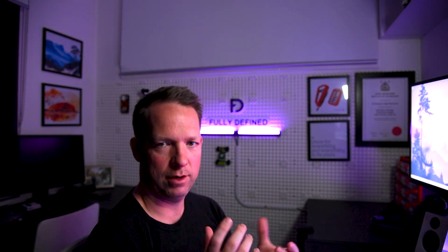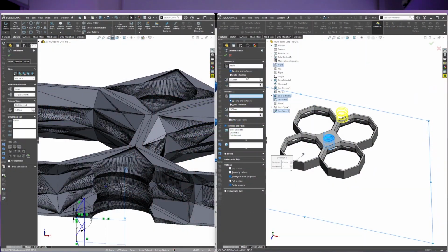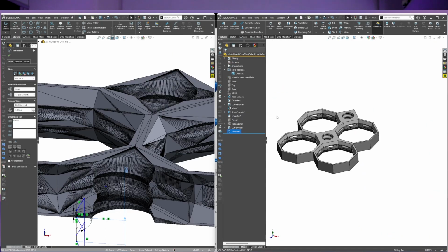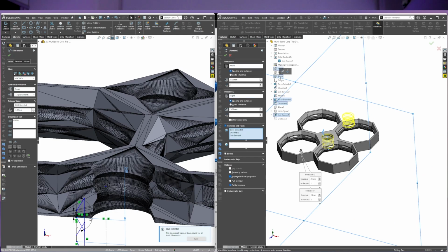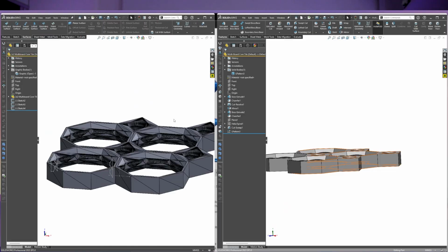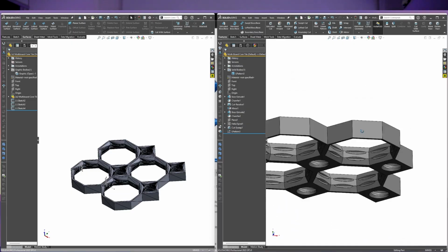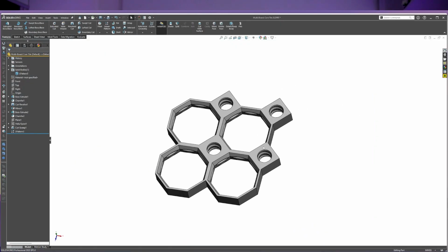In the end, I changed how I did that feature in the sense that when I first created it, I made it a separate solid body, cut the thread, and then did a linear pattern of that solid body and then merged it together. I do change that process whereby I merge the original diamond cut extrude, and then I do the swept cut to that same body. So I'm just ending up with one solid body. I don't actually have multiples, which means that all my pattern features end up being features themselves, not patterning bodies, and not requiring a merge feature later.